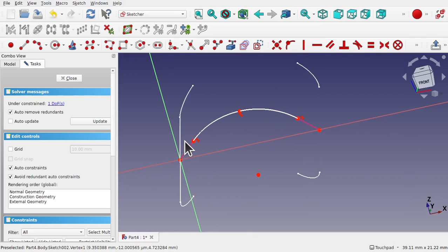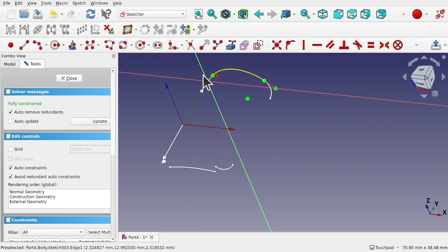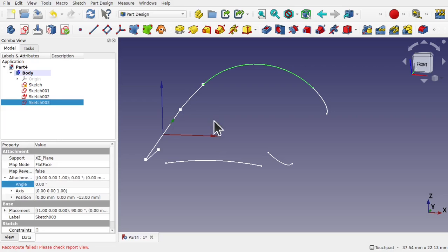When we do the sweep, this will create two parts to this sweep along this edge. For the time being, we're just going to go with the standard single arc that connects up, coincident and tangency. So let's close that and do the same on the other side.